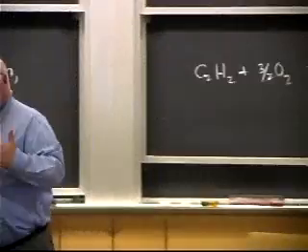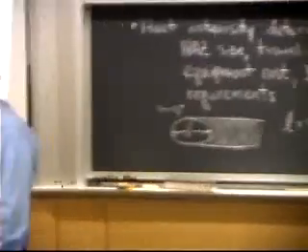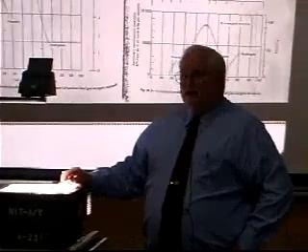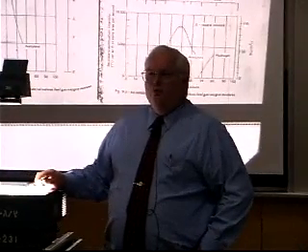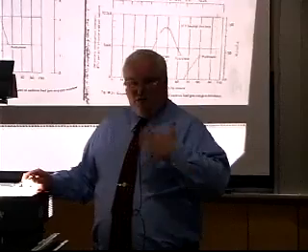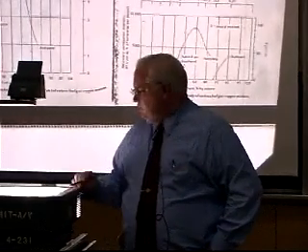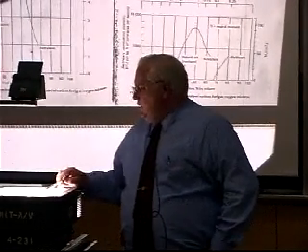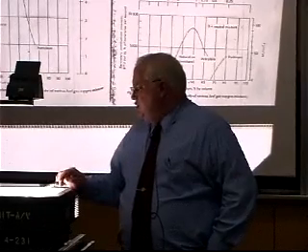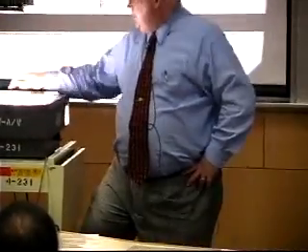That means that you don't get your most complete burning at the stoichiometric ratio. You get it somewhere on the fuel-rich side of that, where you're driving the oxygen down as low as possible, and the neutral point's actually over here. But in any case, you have these peaks, and you get your maximum burning somewhere near the stoichiometric ratio in each case. Not exactly at it, but near it, depending on how you do the calculation.